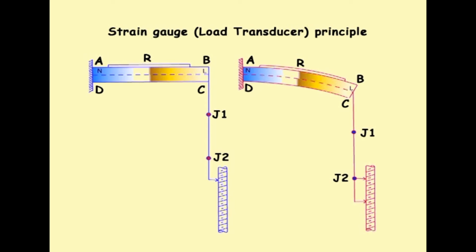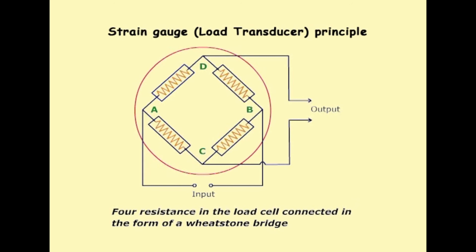When a piece of resistance wire is stretched, its electrical resistance increases. Conversely, if it contracts, its resistance decreases. Further, the change in the resistance value is proportional to the change in the length. When a resistance wire is attached to the upper and lower faces of the flat spring, changes that occur in electrical resistance by deflection of these planes are proportional to the load applied on the specimen. The electrical recording is being done with a Wheatstone bridge, which contains 4 resistances.